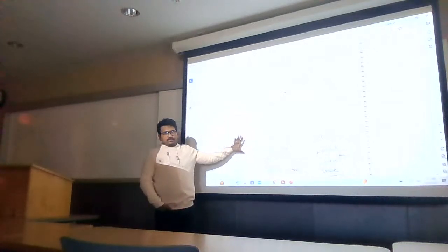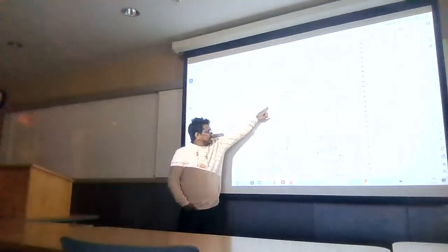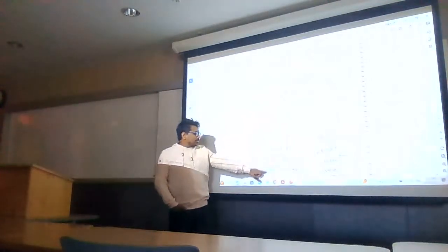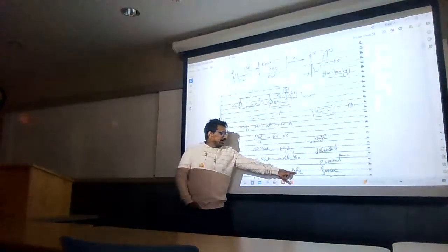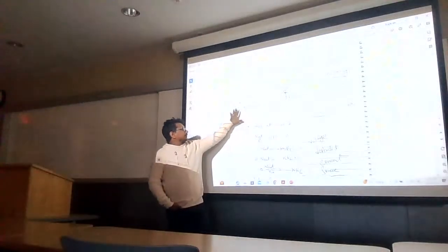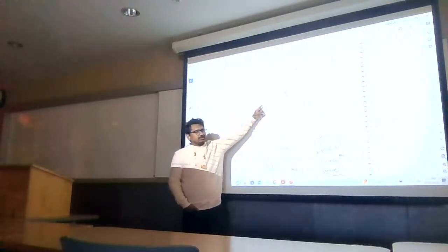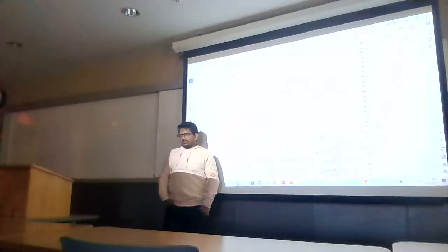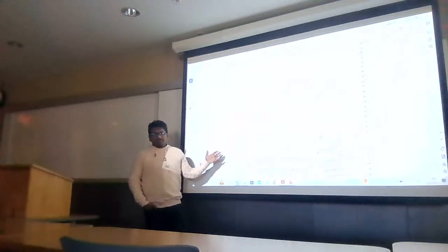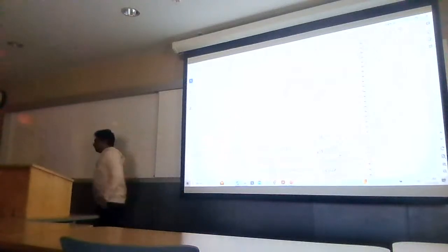If you go through the basic circuitry and how an amplifier works, you will find that, let's say, if I calculate KCL in here, the output and input relationship, which is also known as the gain, is minus gm RL. Which means in this circuit we need something that can produce a current depending on the voltage. And the BJT and MOSFET, these two devices, are also known as voltage dependent current sources. These devices can produce current depending on voltage. So this is the message I want to give you.